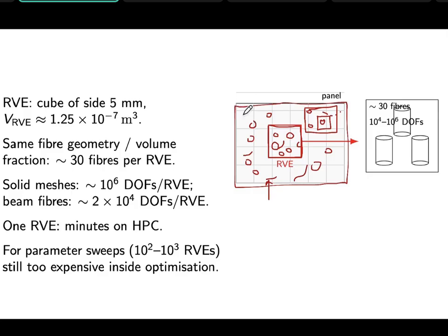into account. So when you select a representative volume element, meaning something that represents the microstructure or whatever you're modeling, think that what you are representing here is something that needs to be representative, so meaning large enough that it includes enough of the statistical meaning, but also something which is sufficiently small that it doesn't take ages to compute. Okay, so that's what you'd need. And if you do that, then you can use whatever method.